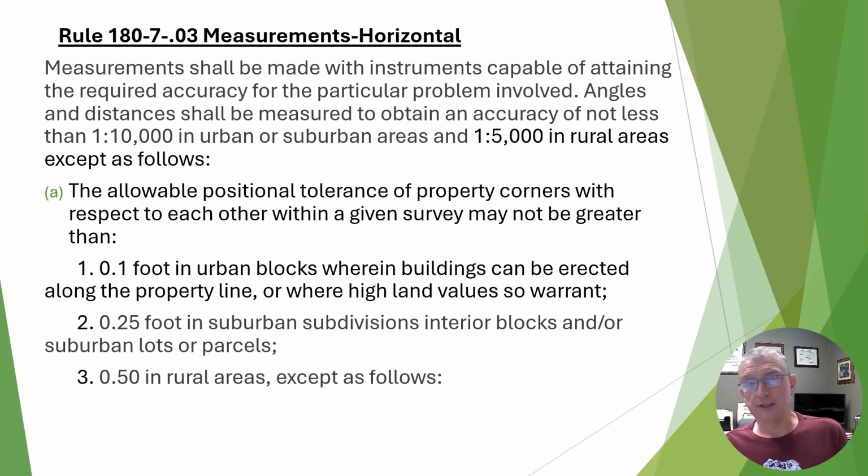Now, understand that it's kind of an either or, and yeah, there's a gray area. If you're surveying a huge, say 640-acre parcel, which is a square mile, so it's 4 miles around it. If you have a 1 in 5,000 closure, it means you've got 4 feet of bust. Might be in one place. You might have 3 lines measured pretty good. You might have 4 feet of error in one line, but you're still compliant with a 1 in 5,000 closure.